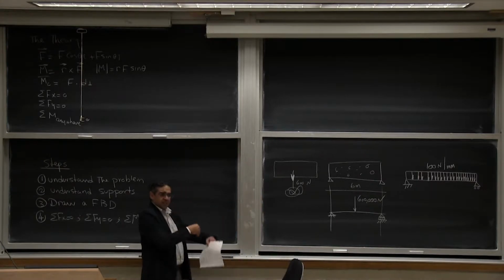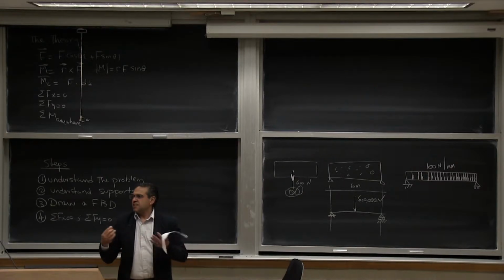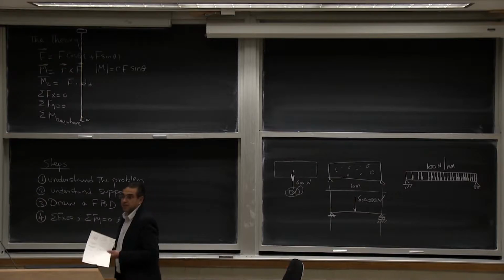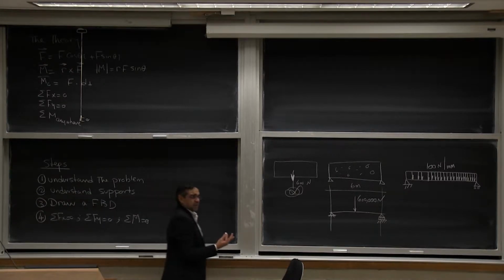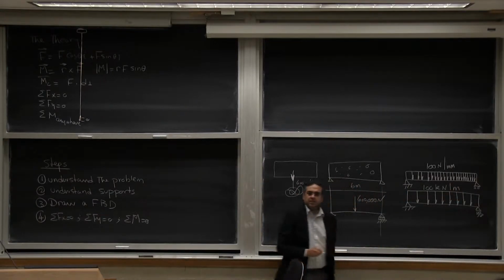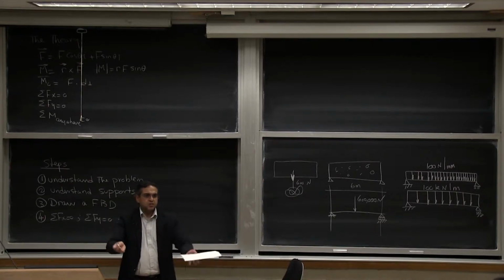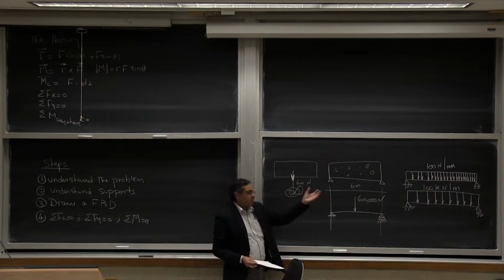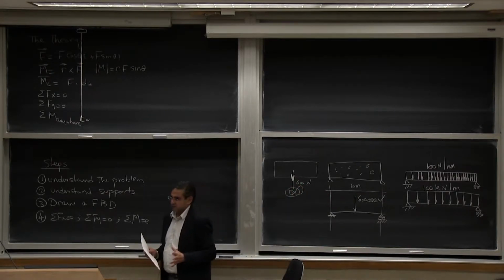Okay? So I divided 600,000 by 6,000 millimeters. Then I managed to calculate that there are 100 Newtons per millimeter. That's more accurate. I could make my life a little bit easier and represent it as 100 kilonewton per meter. So that transfers to you that what I have is actually a distributed load, not a concentrated load. This is more accurate.